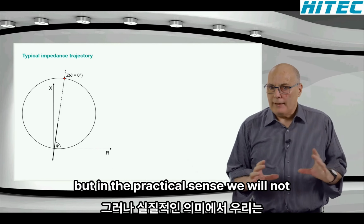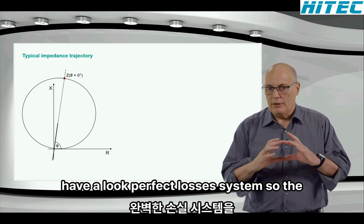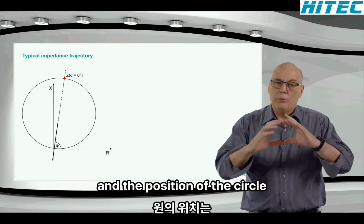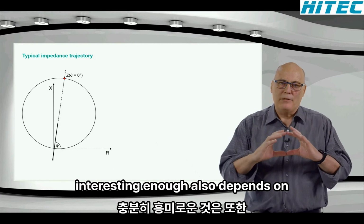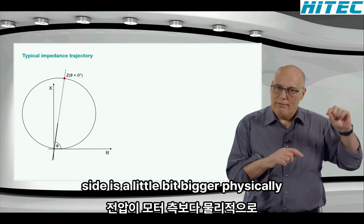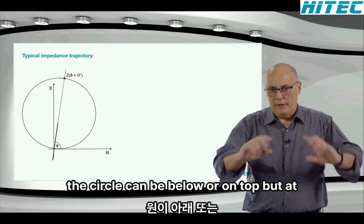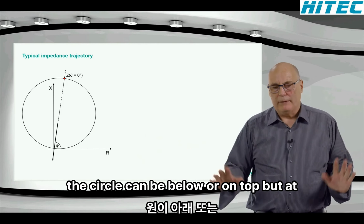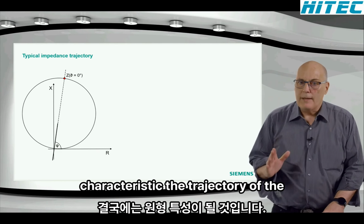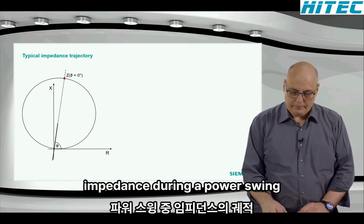But in the practical sense, we will not have a perfect lossless system, so the power swing trajectory will be a circle. And the position of the circle, interesting enough, also depends on whether the voltage on the generator side is a little bit bigger than on the motor side. The circle can be below or on top, but at the end of the day, it will be a circular characteristic, the trajectory of the impedance during a power swing.